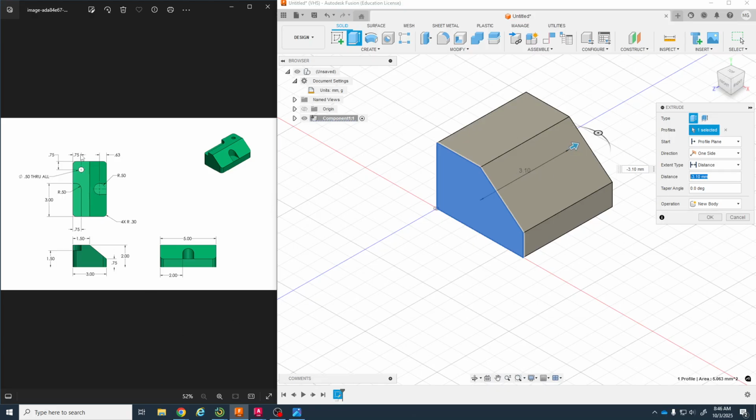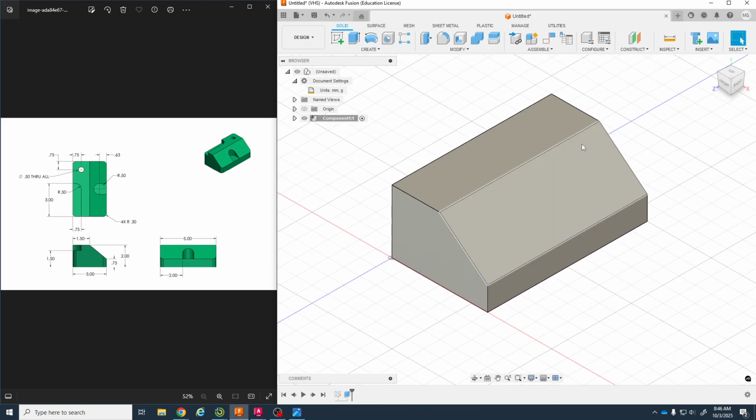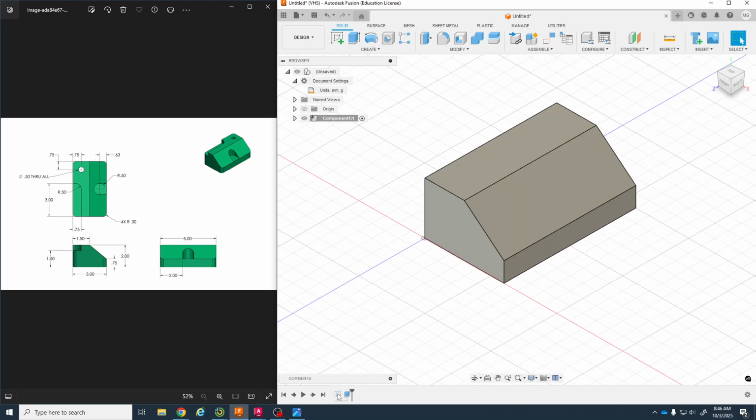The depth of this object is 5, so I'm going to type in -5. So my sketch gets extruded -5 millimeters. Okay, now I have a sketch down here and my extrude in my little, what is this called? History bar or something? Okay, next part.